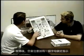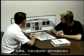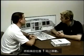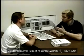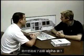You take off flaps position 1 plus F. After rotation, you notice that you have an alpha lock indication below the flap number. What is that alpha lock indicating? Alpha lock, which truly indicates a slat lock, means that I cannot retract the slat from position 1 to up. I can retract it from any other position up to position 1, but I cannot go any less than position 1. What creates that alpha lock?